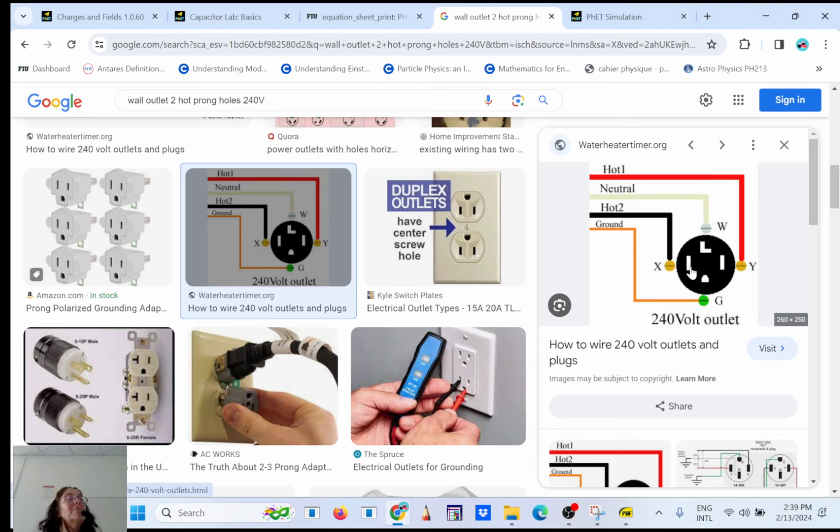by the way, I was doing this with my other class, but you see those outlets here that you use for the big washing machine or the dryer or the AC unit. Do you see instead of having three, it has 1, 2, 3, 4 prongs here, and you have two hot lines. So one hot line is at minus 120. So see, this is ground level, so minus 120. And the other line is at 120. So what's the difference between 120 and 120?